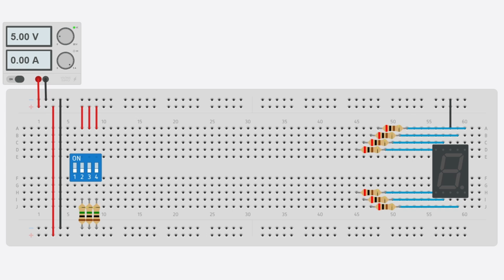And to do this, we simply connect the resistor between the other side of each switch and ground. This way, when the switch is open, the downstream side will be connected to ground and settle at 0 volts. And that will be a nice clean binary signal feeding our logic circuit. And for our pull-down resistors, we can use a high value of resistance because we don't need them to conduct any meaningful amount of current.